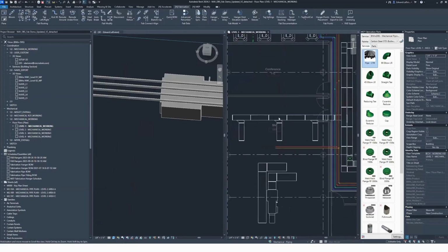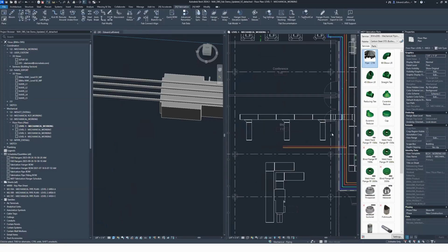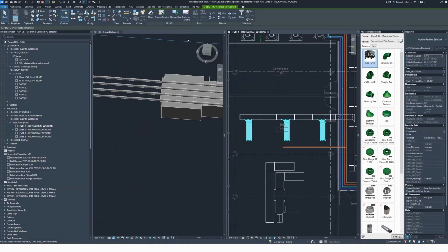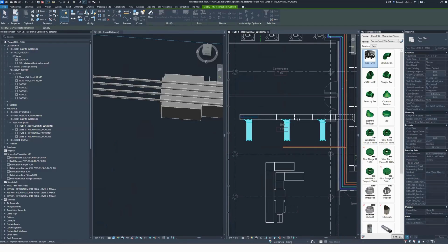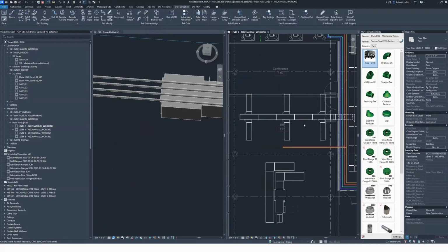So for everyone who's got a whole bunch of routes that you start feeding out, maybe you're doing a little bit of a fishbone distribution here, and you want to grab a bunch of these elements, and you go ahead and use just that mirror tool out of Revit here, just to mirror these guys right down the center. That's all fine and dandy and great, but none of this stuff is connected. It's pretty annoying. So why don't we just rehost it?